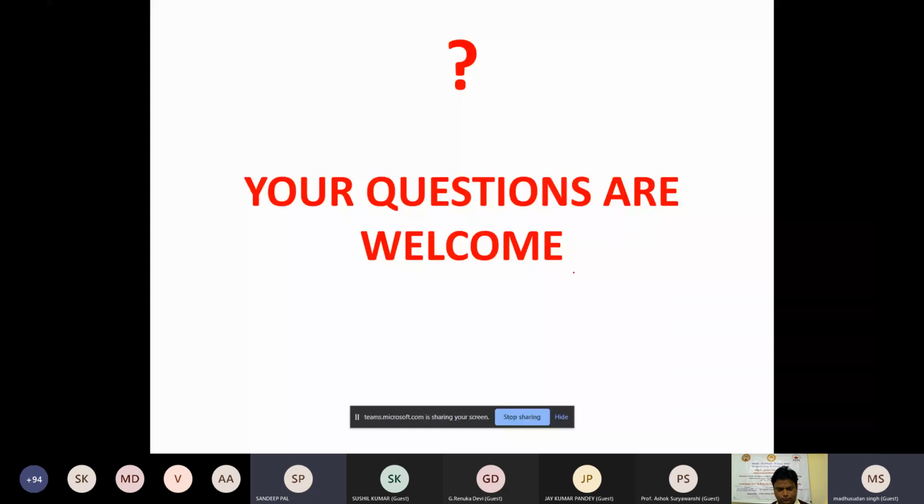What do you mean by control? Are you working on some research work? I just want to know in what reference you are asking this question. Sir, what type of controller can we use in this IC incremental conductance method? Controllers nowadays are of a very wide range. Those who are in research use very advanced controllers like fuzzy controllers and learning-based controllers. But mostly for our study, we have used a conventional PI controller. The conventional PI controller is quite effective in maintaining the DC link, even in varying solar conditions.